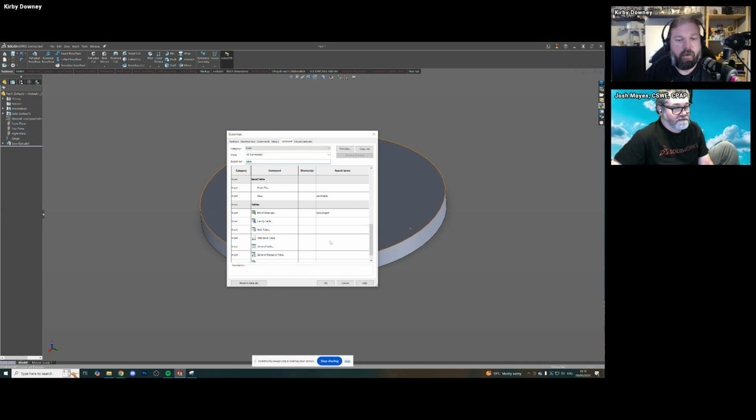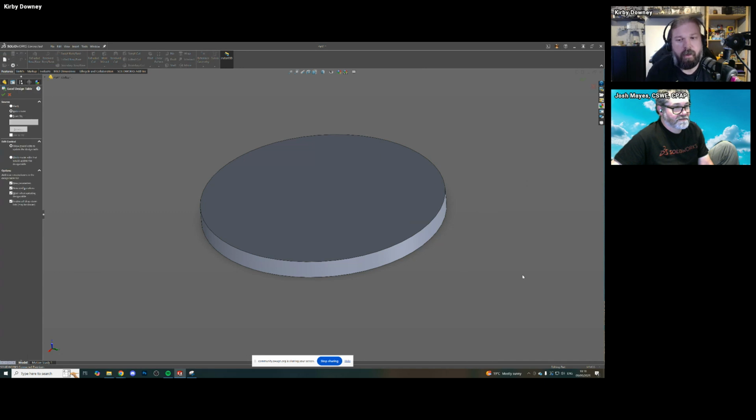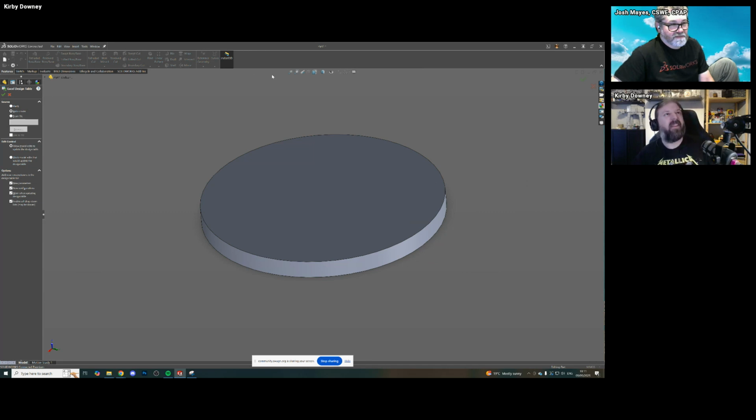You can actually go to the Excel table and assign a shortcut, for example, Shift T. And now every time you press Shift T, you can insert a table. Nice. Another tip to add on to that: if you don't use design tables very often, add them as you need them.